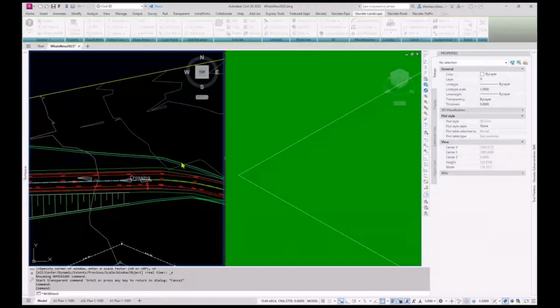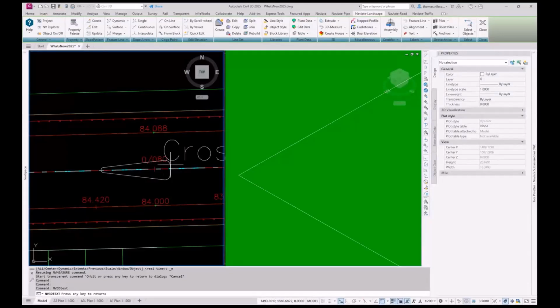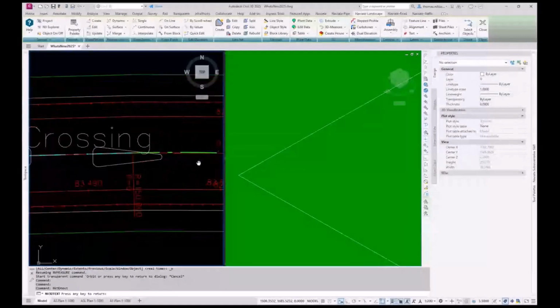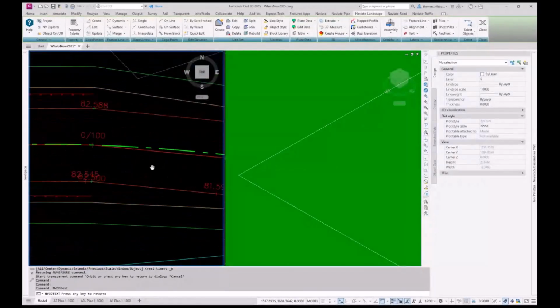We're supporting alignment labels, text, M-text, pipe labels, note labels. I think those were the ones. I'm going to start by doing stationing. Notice that we support station labels, major station, minor station, and station offset labels. If I zoom in, you notice I have a station label 080, 100. So it's every 20 meters.